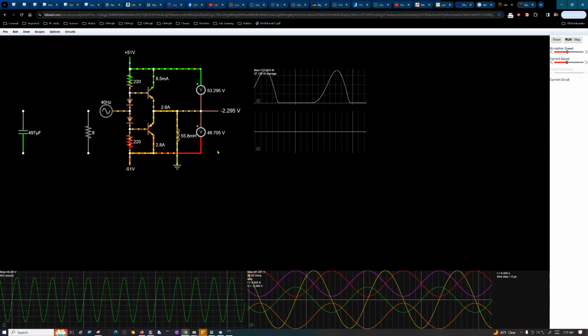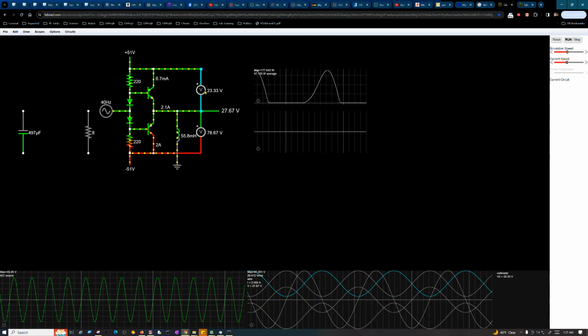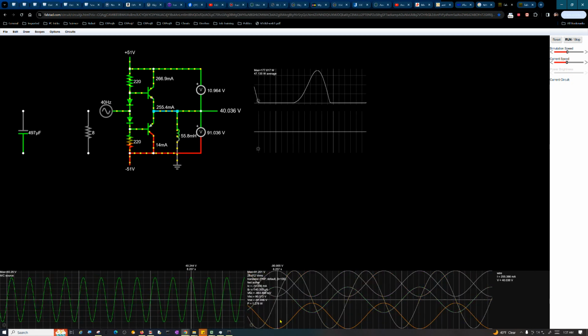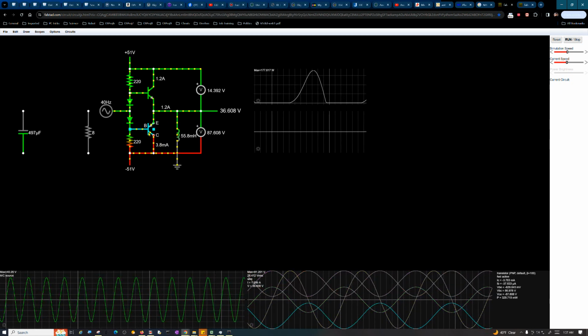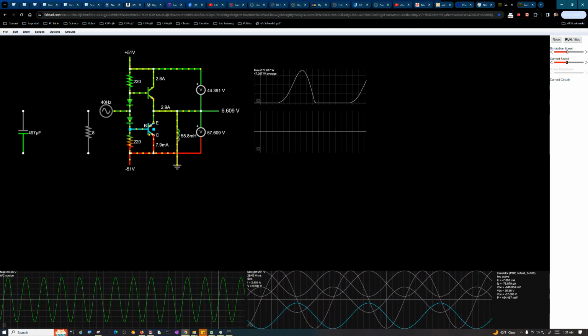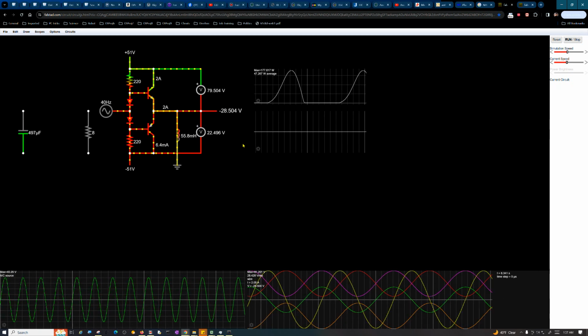Just to finish my point, I went ahead and added this meter to it too, so you can see it's out of phase from this meter by 180 degrees. This other trace, the brown one, is actually the voltage drop, I think, across this transistor. So it's going to be the same shape. It's a negative voltage drop, so that's how it's showing up.